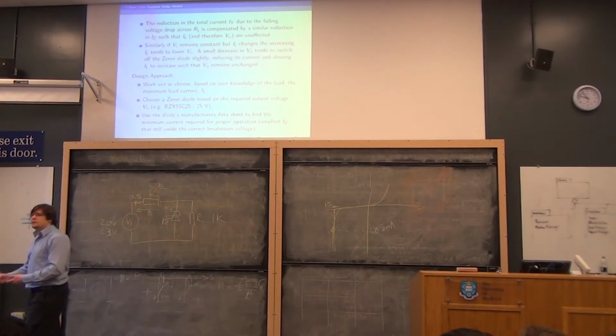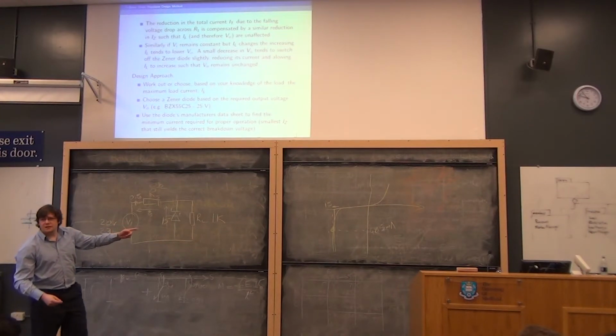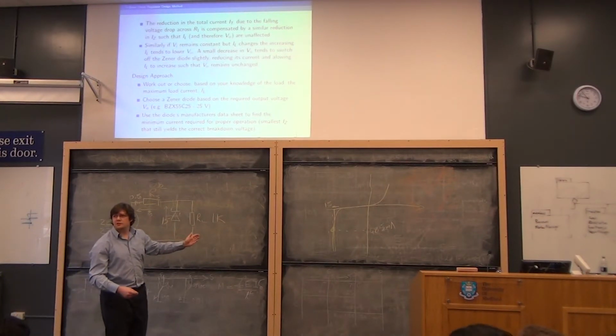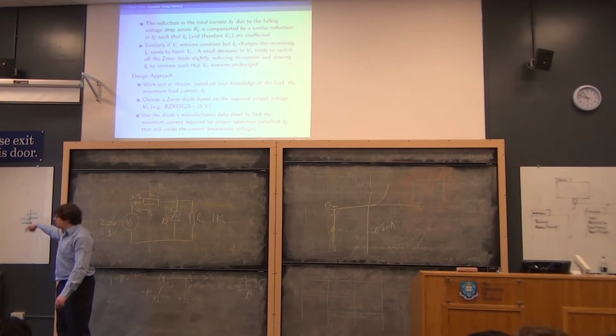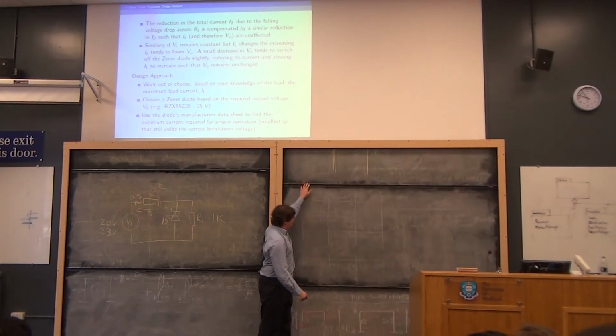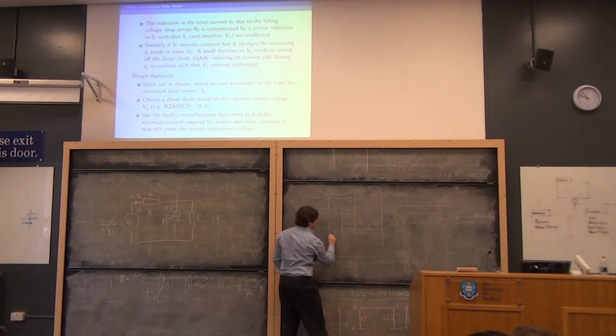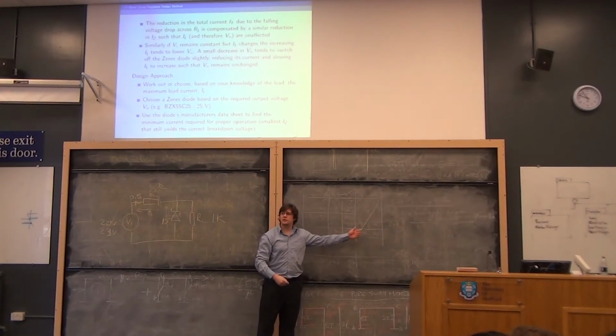I said, well, there's 3 ways of looking at it. You've got a diode that switches on at 0 volts and conducts an infinite current without dropping any voltage, which is that L1. And then there's another one which has got 0.7 volts offset. Same situation. And I said, well, there's a third one, which used to be on the board there, was here like this, where we had 0.7 volts and then a slope line, and we could say, well, the slope line's got a resistance.